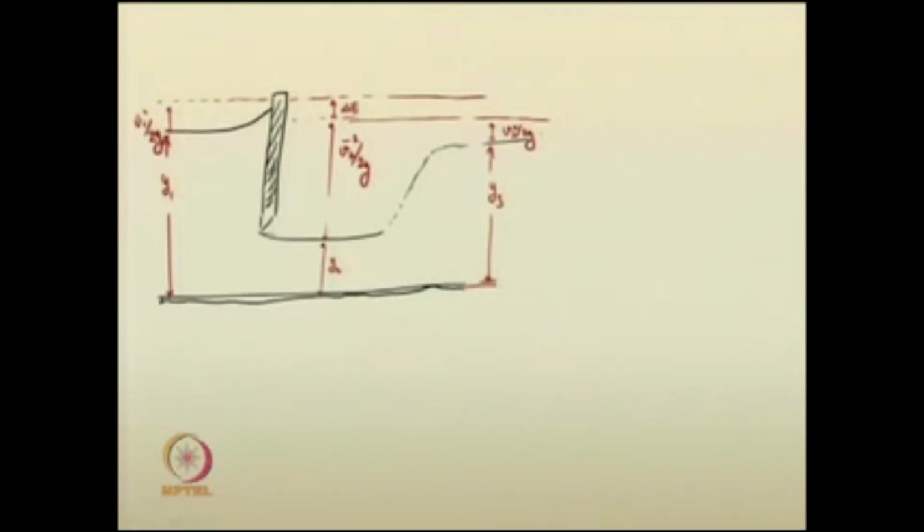And we are drawing an energy line somewhere here, and this is V2 squared by 2g, the velocity head at this section. This is the energy loss between section 1-1 and section 2-2. And if a hydraulic jump is formed here, you can take it as section 3, and this is y3, and this particular quantity we can give as V3 squared by 2g. Okay.